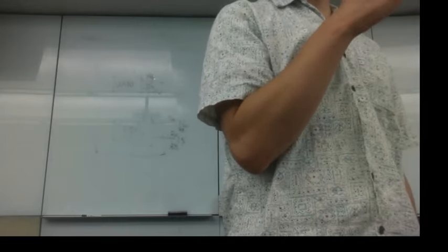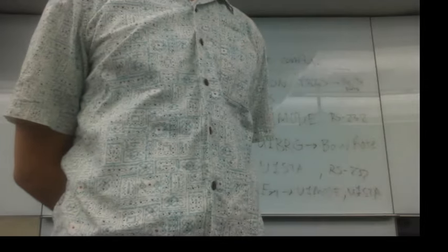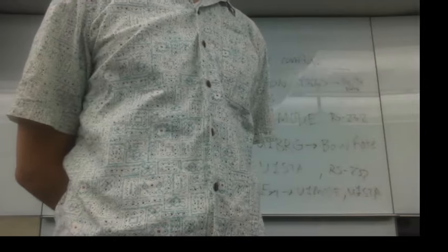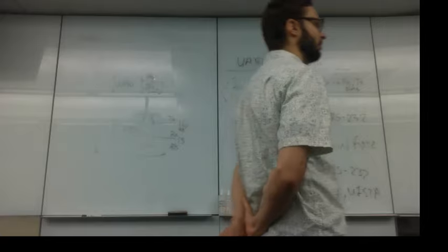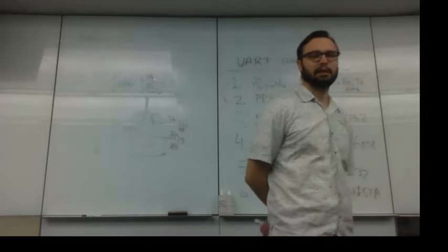So you send a signal up when you're ready to receive data. And there's a signal ground, which makes sure that both computers are at the same voltage level. There's DCE ready, that's the other side saying it's ready. And there's clear to send, which is similar to DCE ready, but that's more for when you're processing individual bytes of data, and request to send.